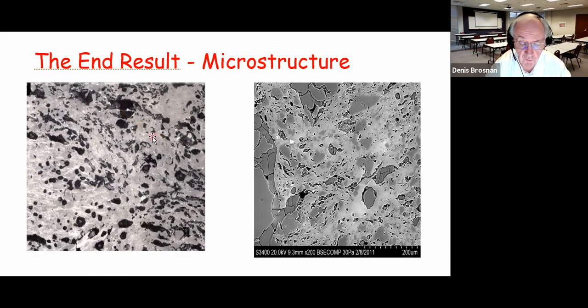These clay particles are what lead to the moisture reabsorption characteristics of bricks, which causes them to expand a little bit over time. And over a long period of time, like hundreds of years, it can cause the brick to disintegrate. The more glass phase that you have here, the less porosity you have here, the more resistant the brick is going to be to disintegration.